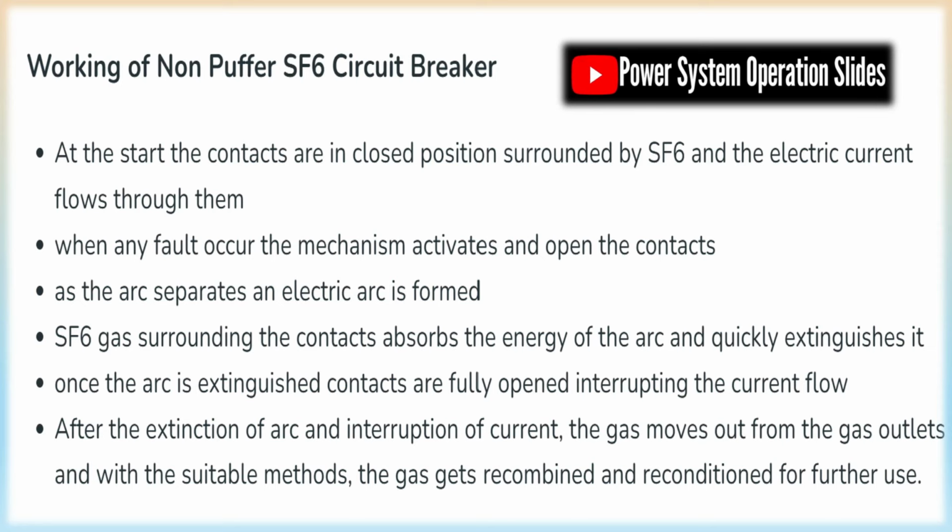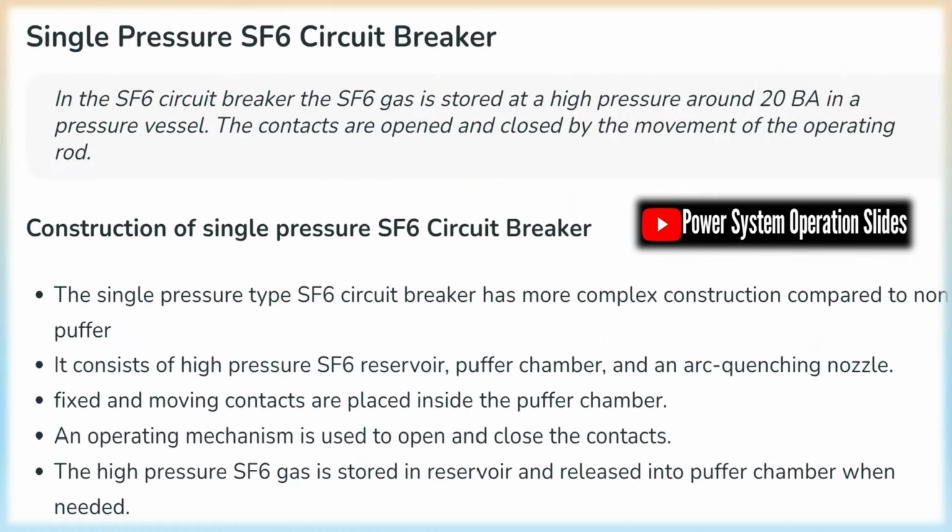Very high electrical conductivity at elevated temperatures, providing low arc voltage. Colorless, odorless, inert, and non-poisonous. Some of the disadvantages of SF6 gas are its high cost, its tendency to form corrosive metal fluorides during arcing, and the fact that it is a greenhouse gas.